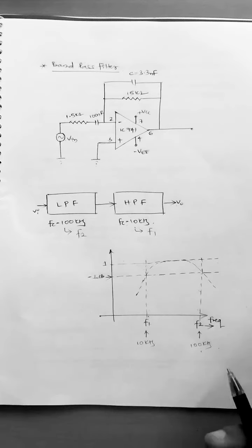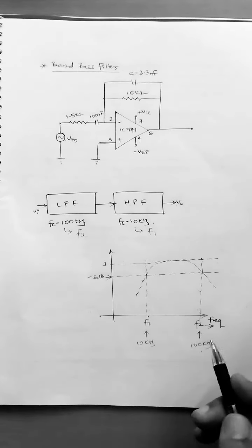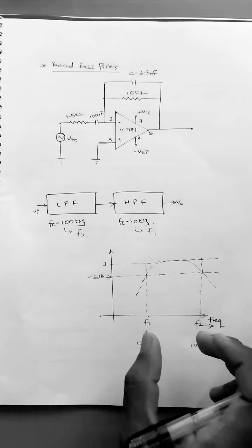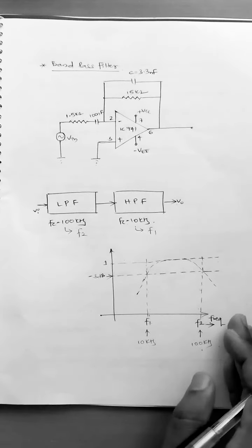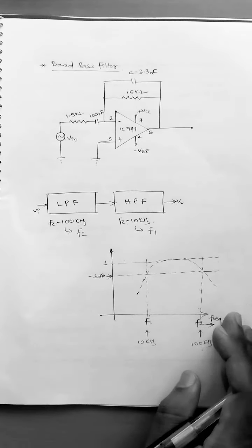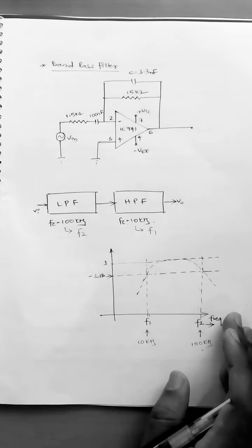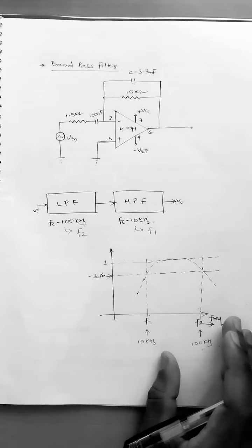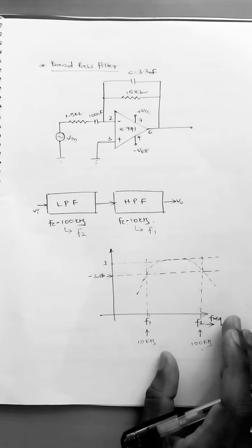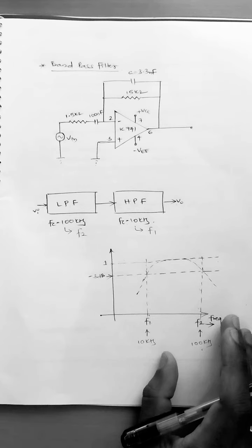One more filter is there. It is called a band reject filter, where it is rejecting the specified range and allowing the remaining frequencies. Now we will connect all these three circuits on the breadboard and we will note down the frequency, output voltage, we will calculate the gain and gain in decibel, then we will try to draw the frequency response of LPF, HPF and BPF.